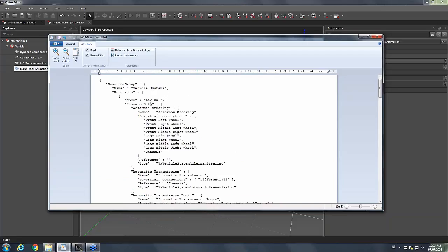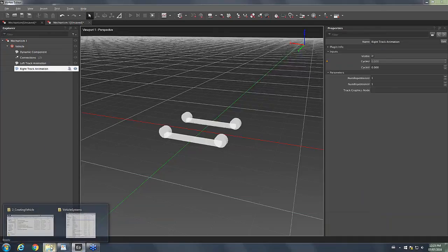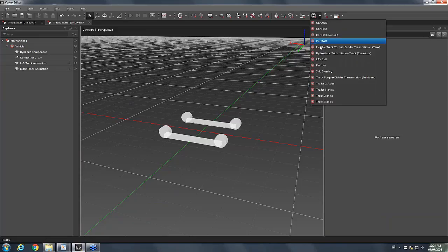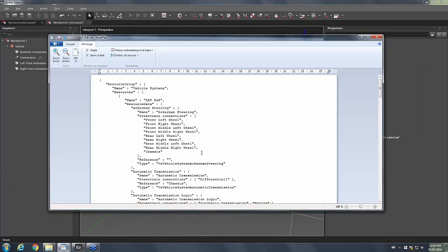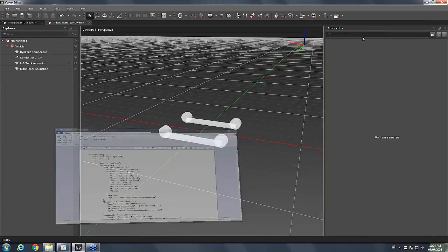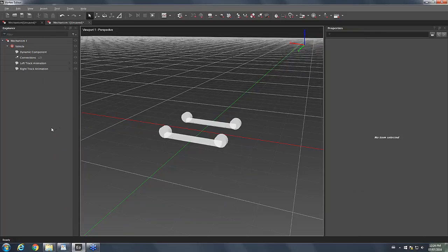By dropping a new preset inside the vehicle system folder, it should appear up here in the listing if you've given it a new individual name and there's no syntax error in your file. If you don't see it appear in the listing here, it's probably because you have a syntax error of some kind in the file. You probably did like me and you forgot to put a comma or close a parenthesis somewhere. So don't feel bad about this. Back to you, GP.